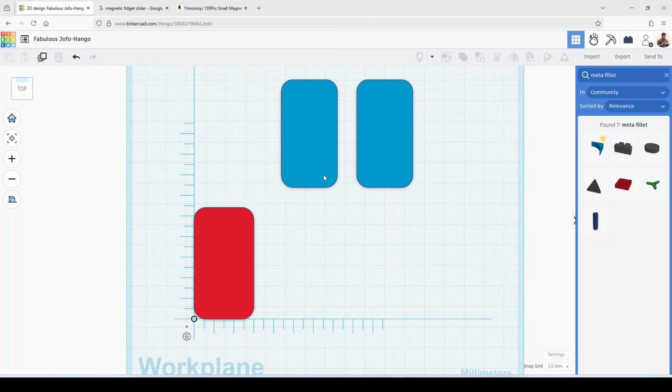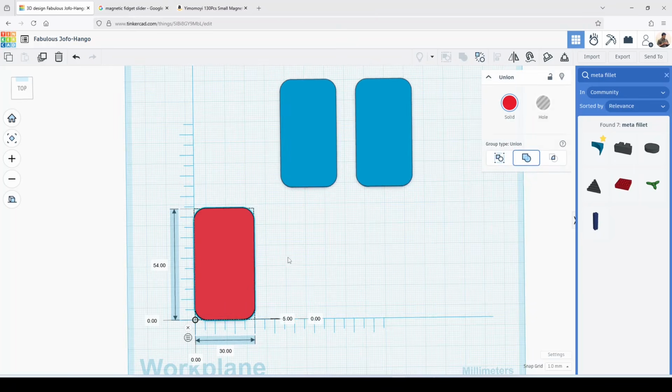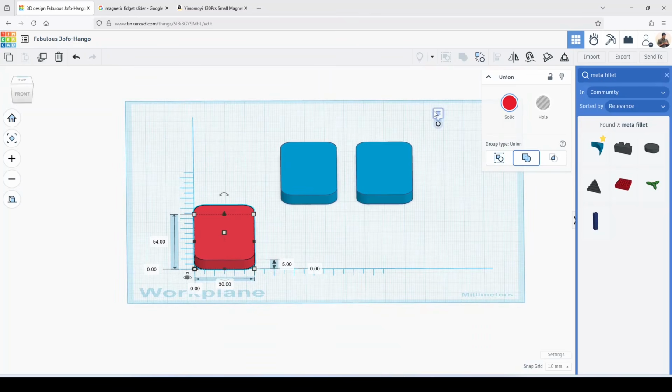Now, what we're going to do next is carve out this box. Remember we did some math over here, so we have the cover being 3.5 millimeters. Sorry about that. We are going to create a space that is just enough for this cover to fit.